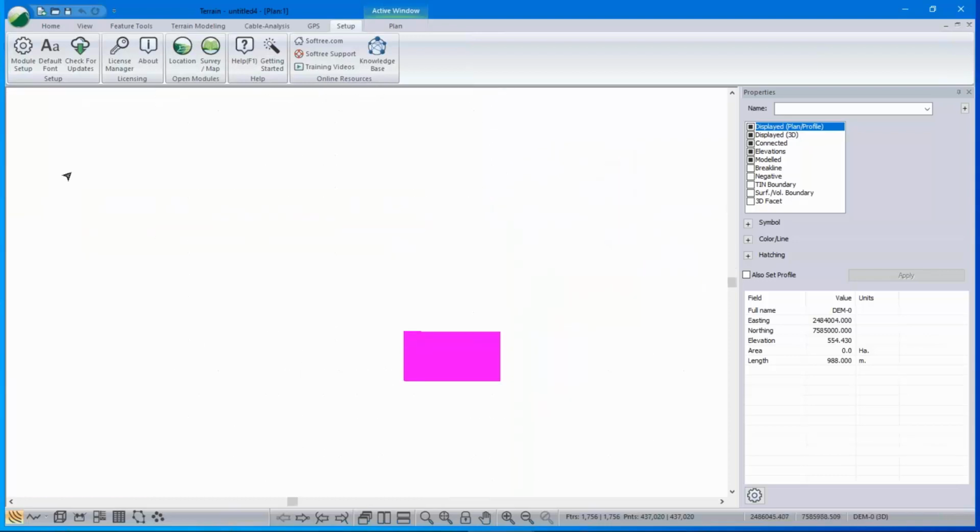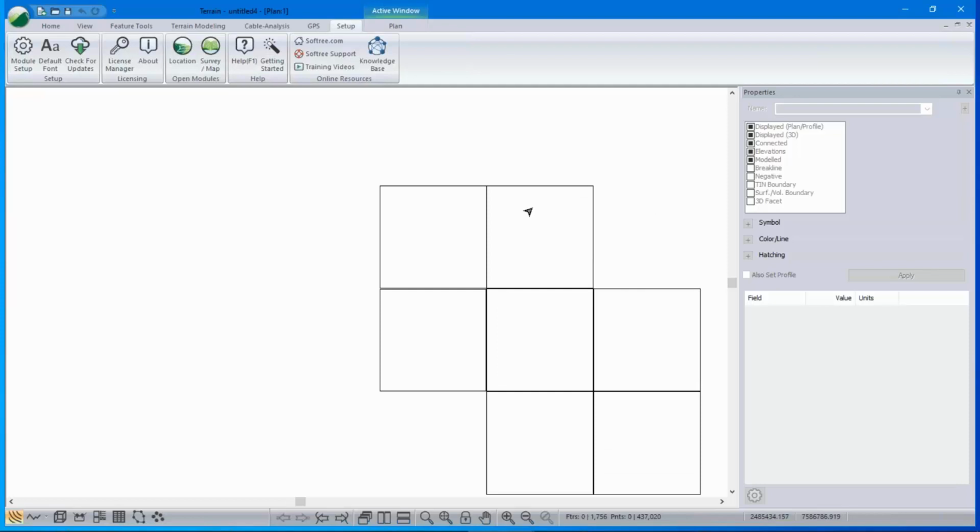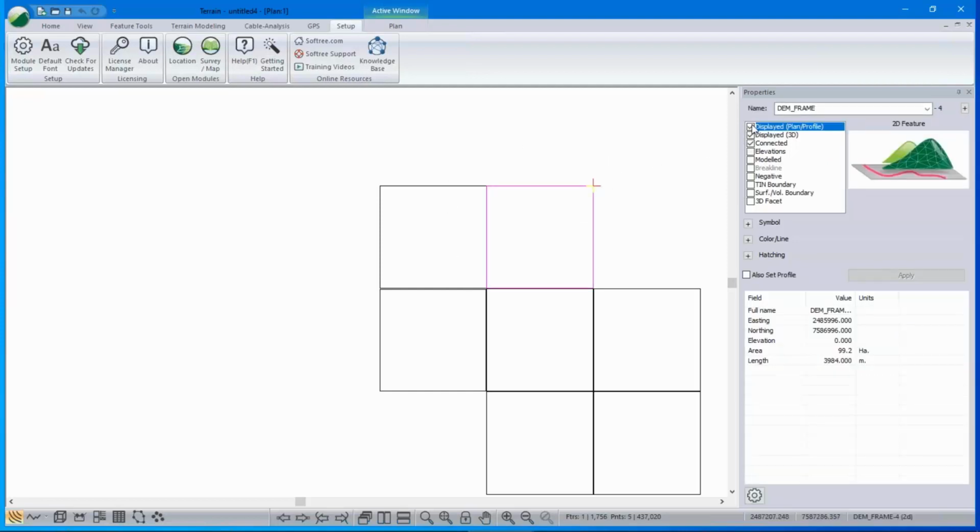And now I can create a model without, there, I just hit the escape key, so it didn't continue drawing it, just drew this hint of where the data is. Or I can click out here, and now there's nothing selected except my tile boundaries, or nothing visible, sorry. Which is another good point. When you're working with large data sets, the data points themselves should be displayed off. So here my boundary is set to be displayed, but my data points have that turned off.